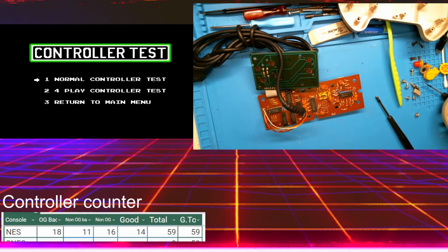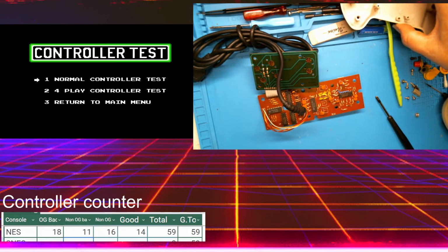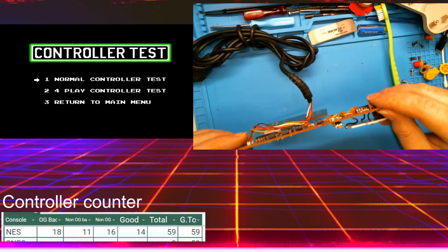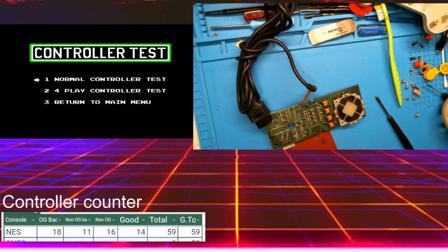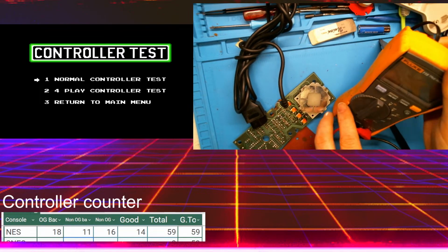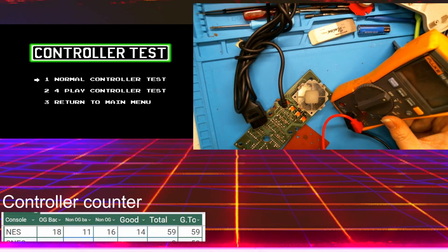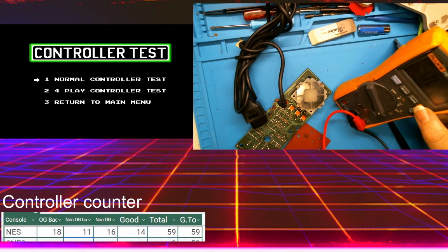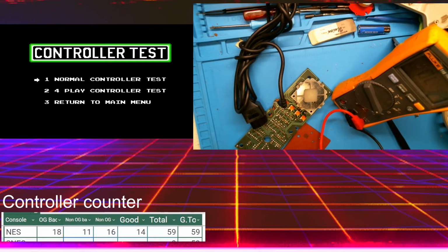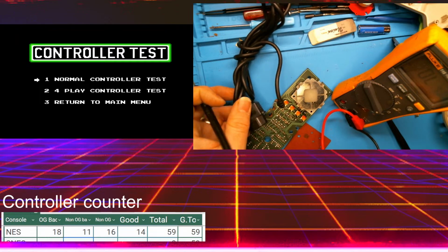I don't know what they were doing, but now I see why they had to make this controller all chunky. Alright. First check the directional. So I will get my meter out here. I don't know if you'll be able to see it, but I'll put it here at an angle. You might be able to. Let's turn it on and find out. Yeah, you can see it. It says low, and when it shorts, that's showing that we have continuity.